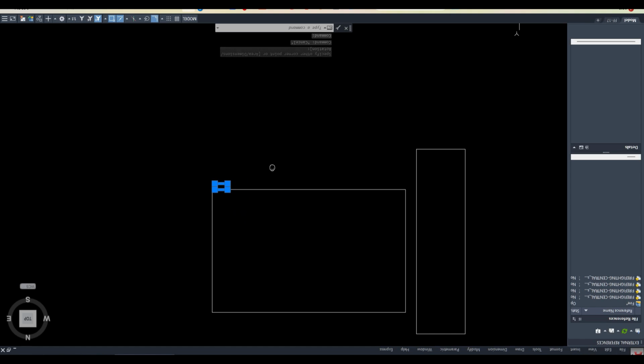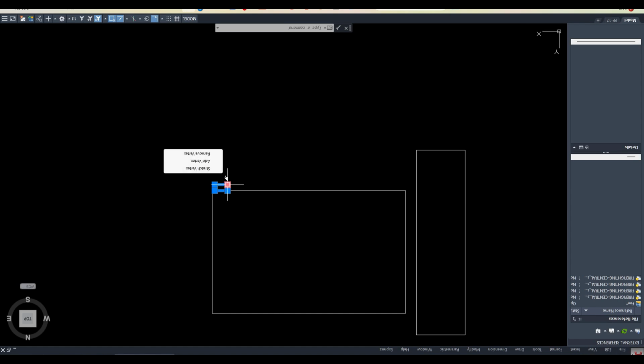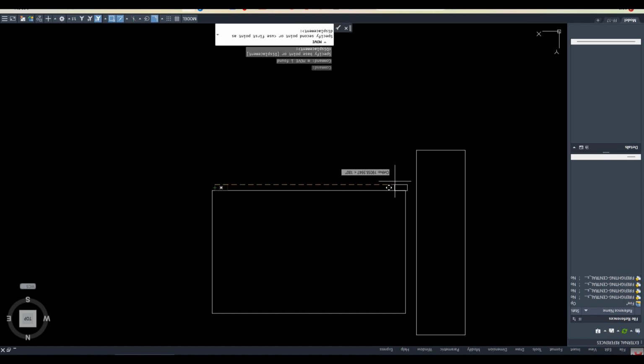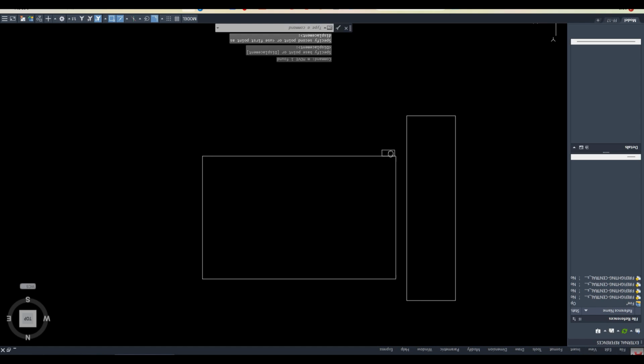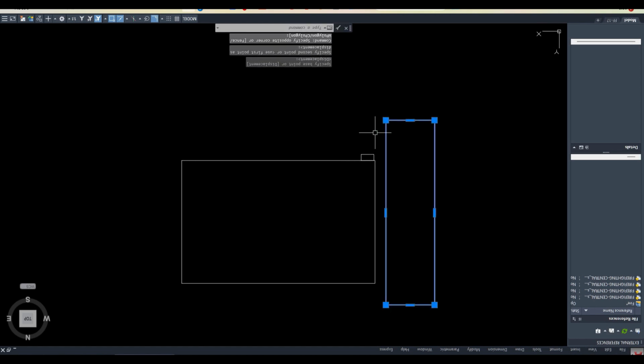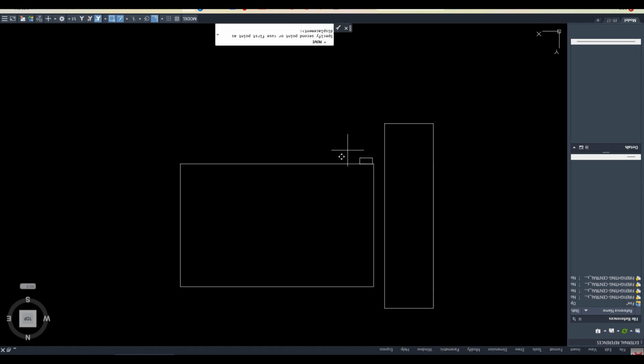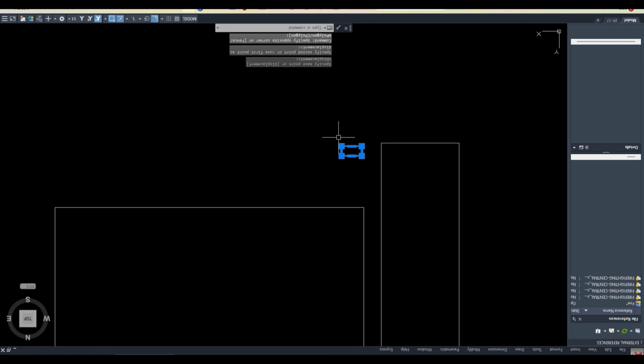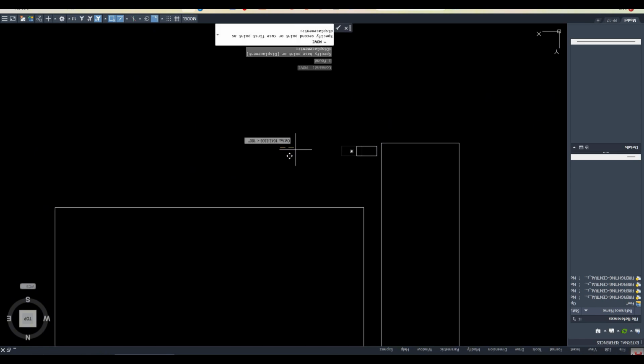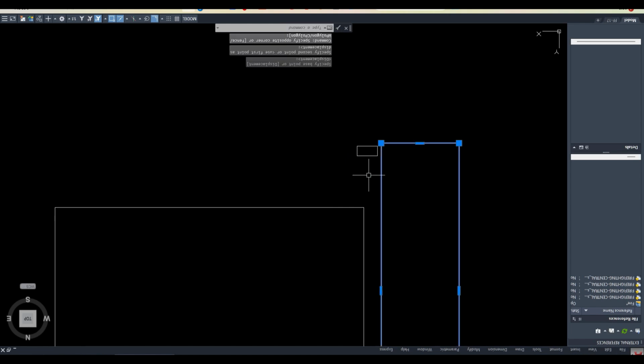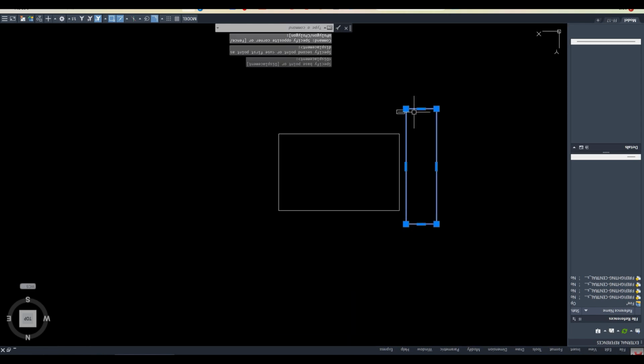No, sir. Why? Because this is not accessible easily. Correct. It has to be accessible directly from the road. And this road and this itself, if you are keeping it away, it should not be more than 18 meters away, and it should be at an accessible location, like nearby the road, from where the truck can come and they can stand and they can connect that breaching inlet.